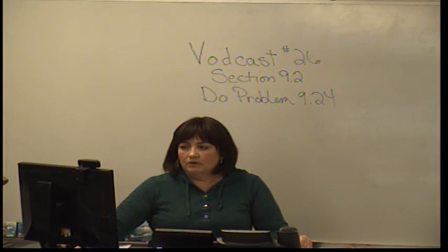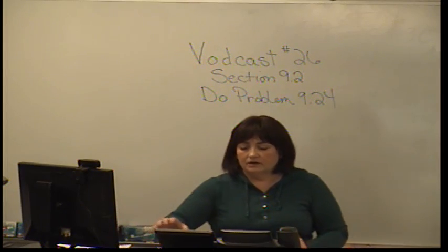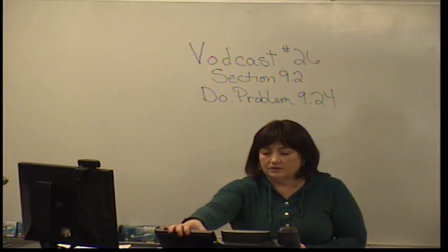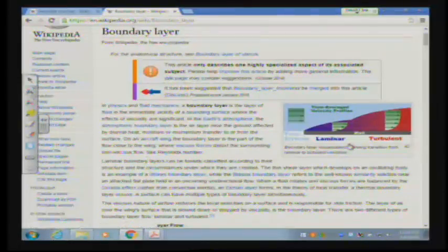So first of all, when we talk about a boundary layer, what exactly are we talking about? So I'm going to come over here to the podium PC, and this is an article from Wikipedia where we talk about the boundary layer, and it's actually very good. But basically, what happens is that you have a layer in a fluid as it's moving that's in the immediate vicinity of a wall of a pipe or whatever it's flowing through or over, where the viscosity effects of the fluid become significant. Now, the way that the boundary layer looks in laminar and turbulent flow looks significantly different.